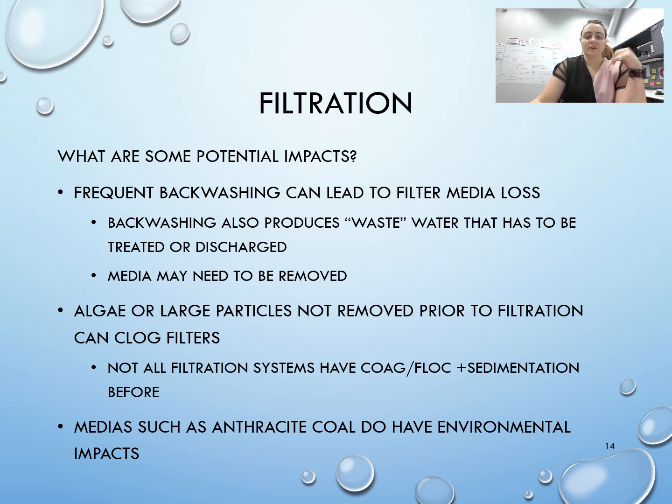If we have algae or larger particles that are not being removed prior to filtration, this can clog our filters. So not all filtration systems have coagulation, flocculation, and sedimentation prior to filtration. Filters can be used without those pre-treatment steps. But if they are, we have to be aware of what things could potentially clog our filters. So water quality has to be good in order for us to make it great after filtration.